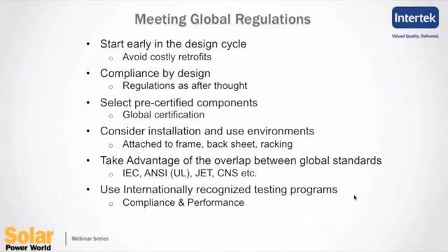Always consider the installation. How you're going to install it, where you're going to install, what regulatory issues are going to come in when you install your components or your product, whether you want to attach it to the frame, or to the back sheet of the modules, or just attach it to the racking system. Each one of them, as I mentioned in the last few slides, brings in different sets of requirements. So understand how that's going to impact your regulatory compliance issues and how it would add additional testing and certification requirements.